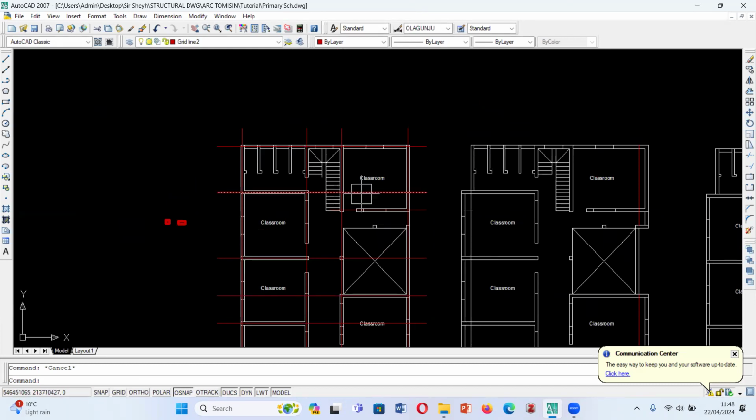these are some of the things you should consider. Number one, you should look out for your wall alignment on each floor. Look out for your window openings. Look out for your door openings. Then look out for any other opening. In addition, look out for your open areas.